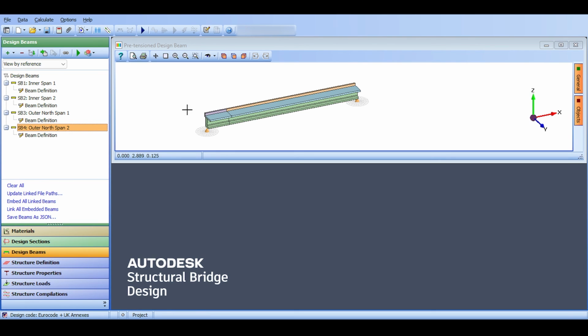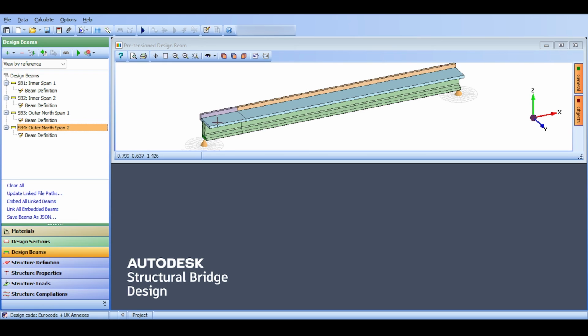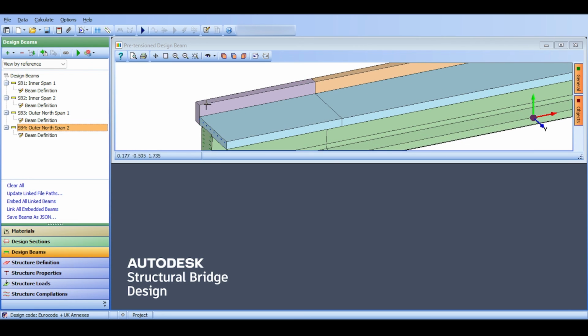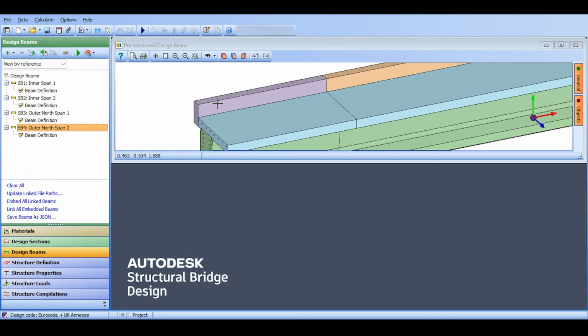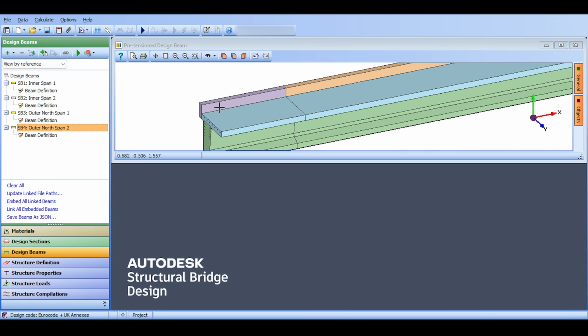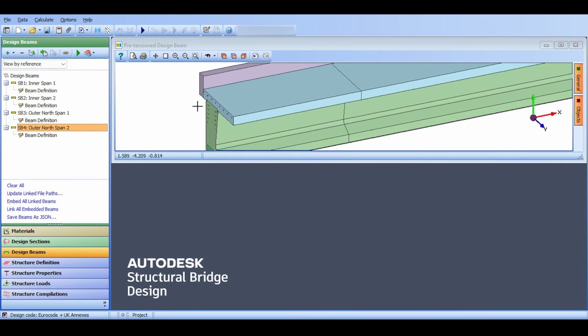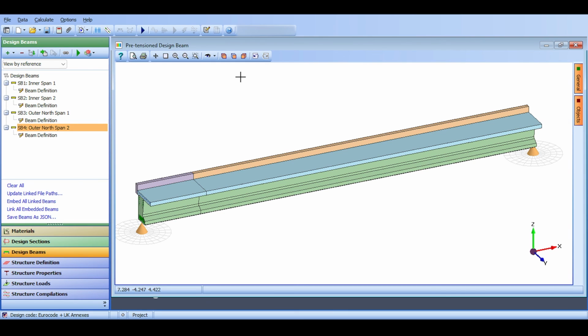There's one final thing that I will not do, but it's regarding the gradient and the barrier. It's because I have a barrier here. The temperature gradient kind of changes because the barrier is a further thickness on the beam, but I'll just leave it. I will not change the temperature gradient. We have defined in this video our design beams, and we successfully copied it, reversed it, understood different aspects of the design beam. So yeah, that's basically everything I wanted to talk about today in this video.